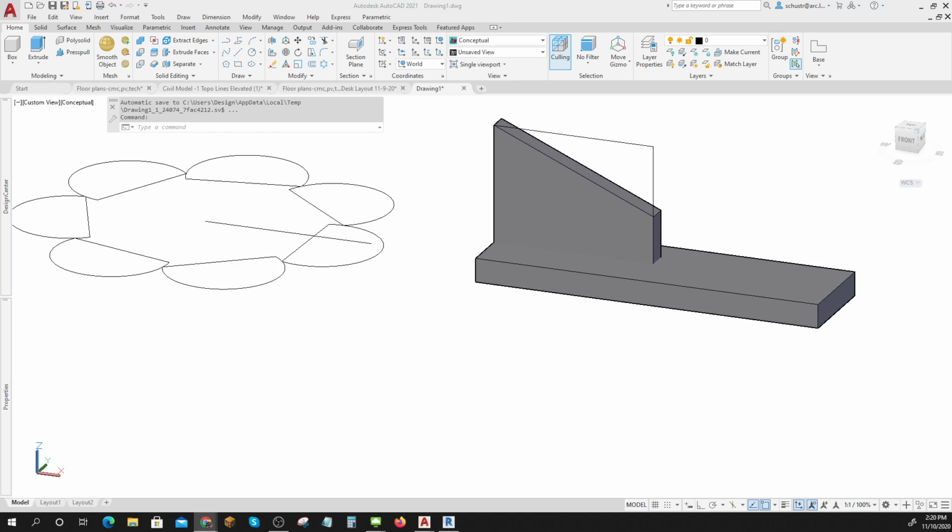So what you've got, you don't have a solid. You have surfaces because you were press pulling the things. So yeah, go back to that one. That's good. Nope. Go back to where you were with your other one. Okay, there you go. Now, what you're going to want to do is erase the two little lines that are coming away from the main cylinder. Erase those.